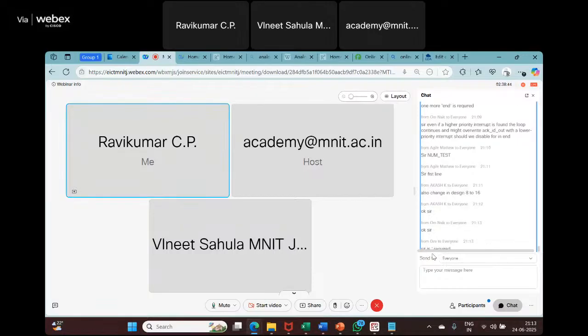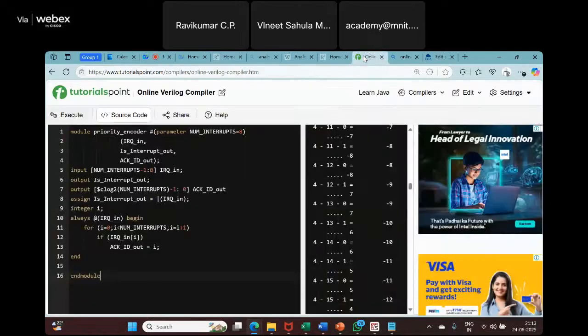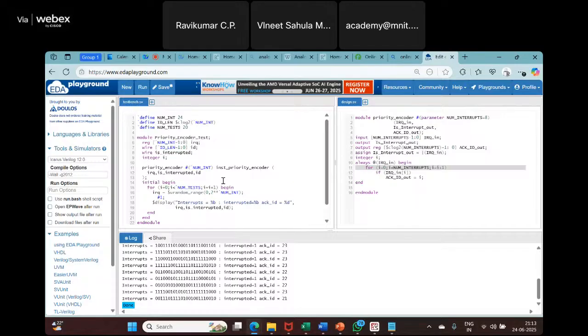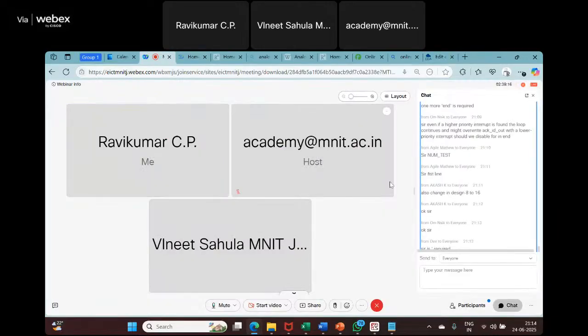Yes, yes. I think he wants to know whether this backquote is required. You must put that when you are doing hash define. Okay. I think his question is this backquote is required. Yes, it is required. In parameter, we don't put. See, if it's a parameter, we don't do. But if it is a macro definition, we have to put backquote. Okay. What else?